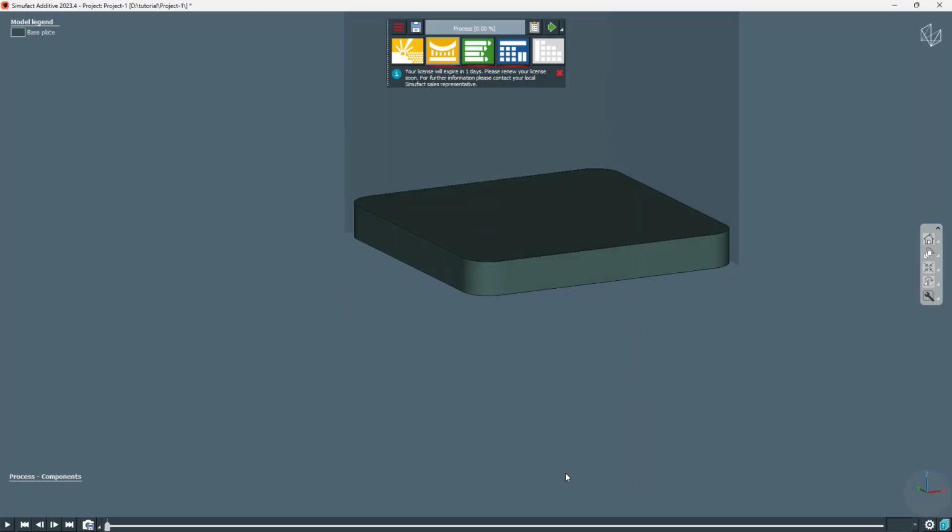Yes, it is necessary. First should be build, then cutting, then support. Then click OK. What about immediate release? Immediate release means it will release all atoms from the base. Cutting means you can give a direction of cutting, and we had seen the animation where it will incrementally remove the material. Like that we can do. Right now we will keep the cutting.